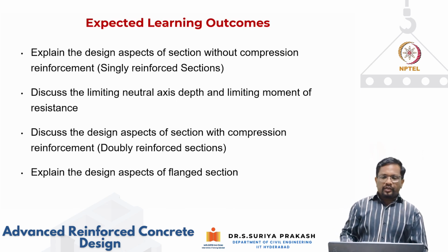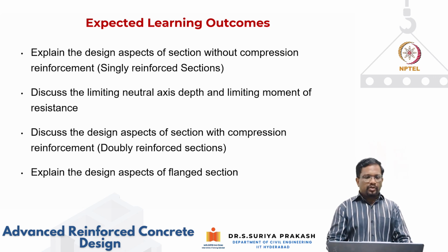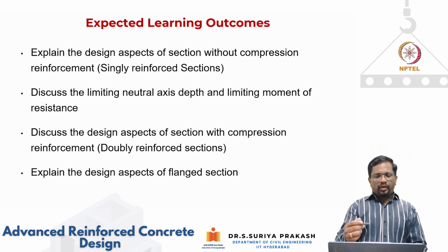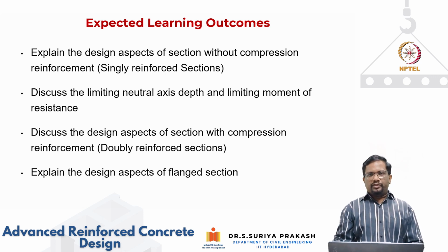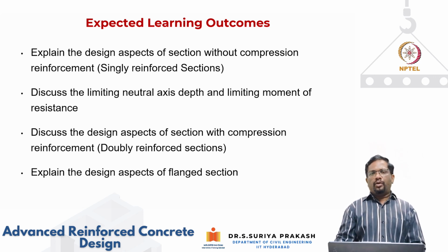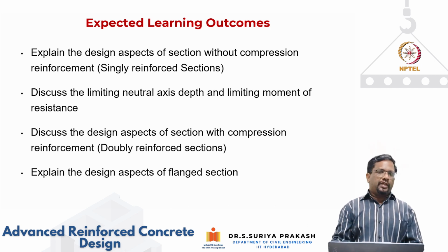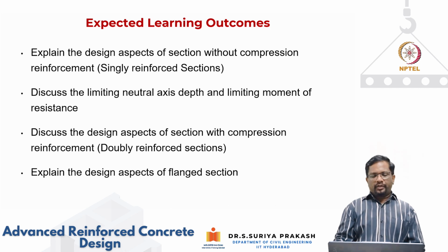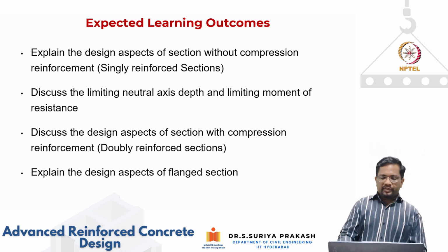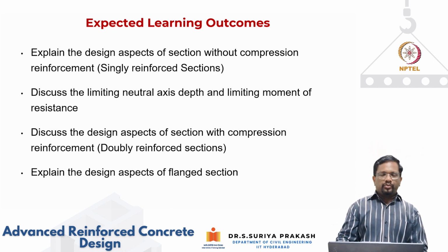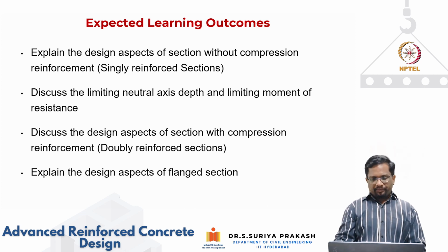The expected learning outcomes are how to design a singly reinforced section using IS code provisions, and how to derive the limiting neutral axis depth and limiting moment of resistance using code specified provisions, including the design stress strain curves which are specified by IS 456. Then we will move on to how to design a doubly reinforced section. When you need a doubly reinforced section, how do you do the design? Those things we will discuss, and then we'll talk about how to analyze and design a flanged section.